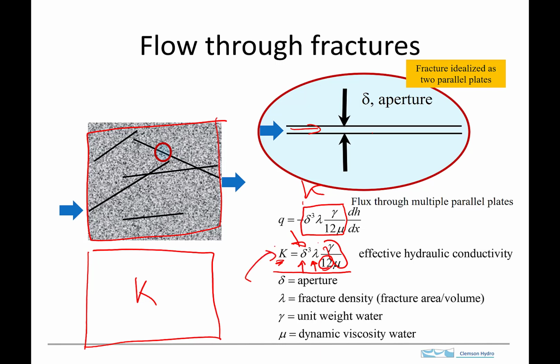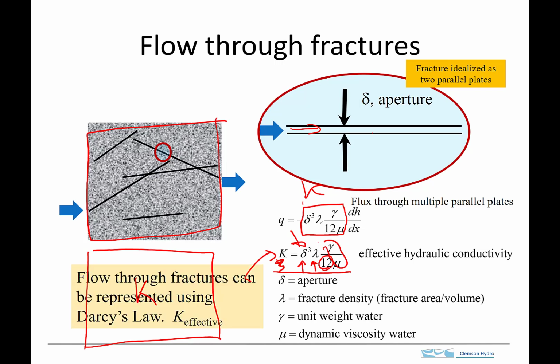And that's important because that would allow us to analyze flow through a fractured system using models like MODFLOW that are based on porous medium. This hydraulic conductivity is viewed as the effective hydraulic conductivity, or the effective porous media analog to this fractured system. And then this is what we conclude.